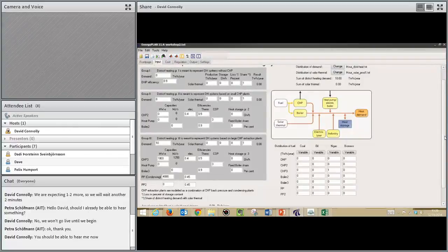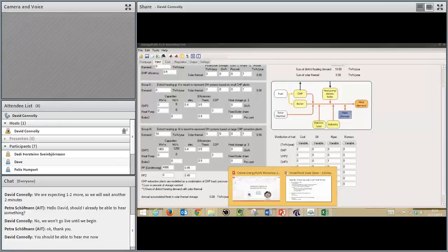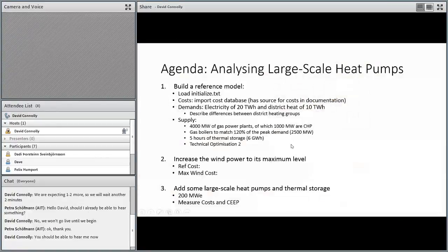On a district heating system, not only do you have CHP plants, but you very often have boilers and thermal storage facilities also to facilitate how these CHP plants operate. And in my agenda, I put in some golden rules that we typically use if we're designing a system that we don't have statistics for.